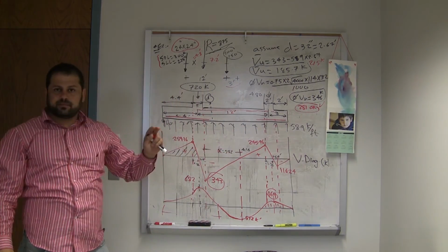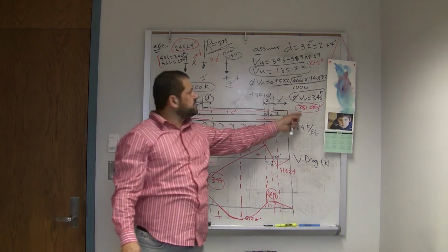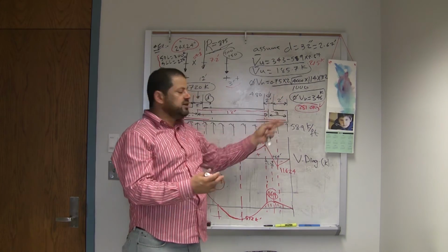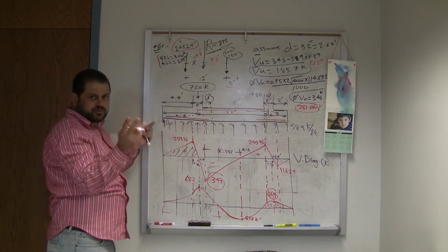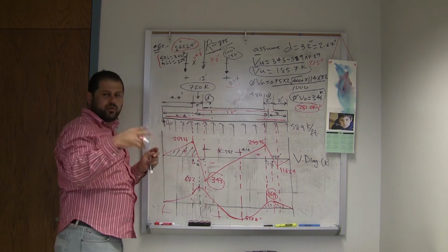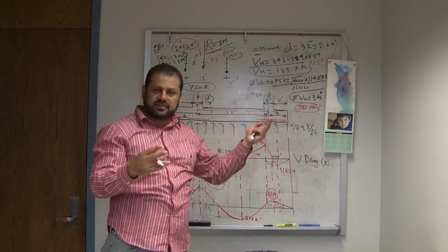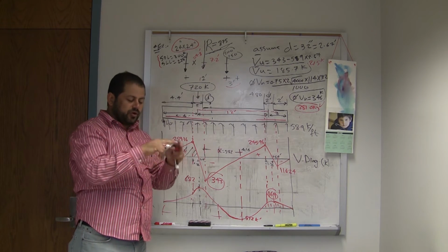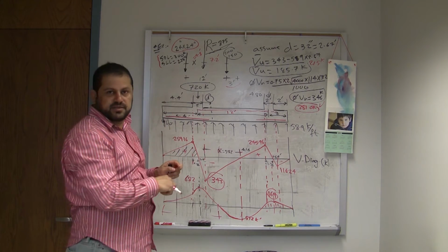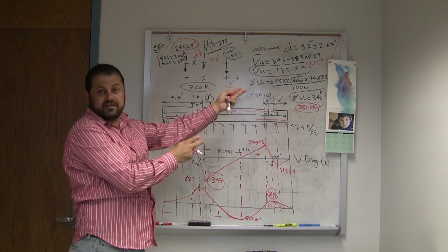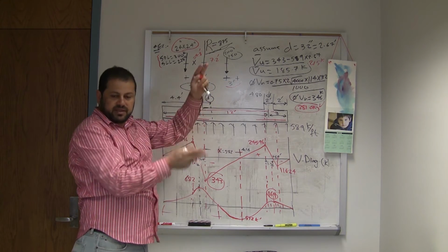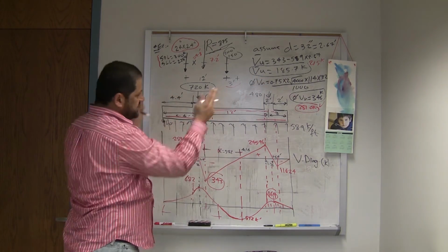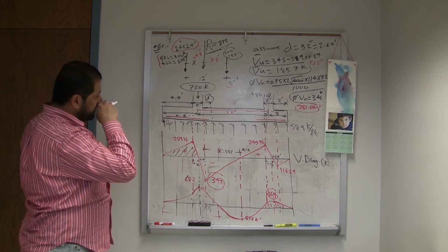It's a little bit bigger than needed, but that's fine. It will save you some steel if you increase D. If you want to drop it a little bit more, that's absolutely fine, especially when you work with the metric system, where you would be finding this in centimeters. But usually we like to have the thickness of the footing going by 3 inch increments. So you can maybe drop it down to 27 and check. The overall thickness is 27 inch, which is 2 foot 3 inch. But this is okay for me. I will do it this way. So now this is D.